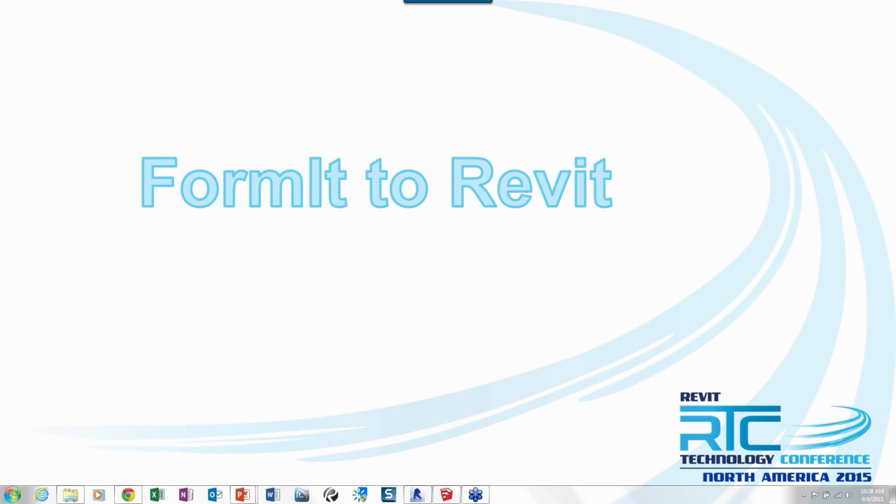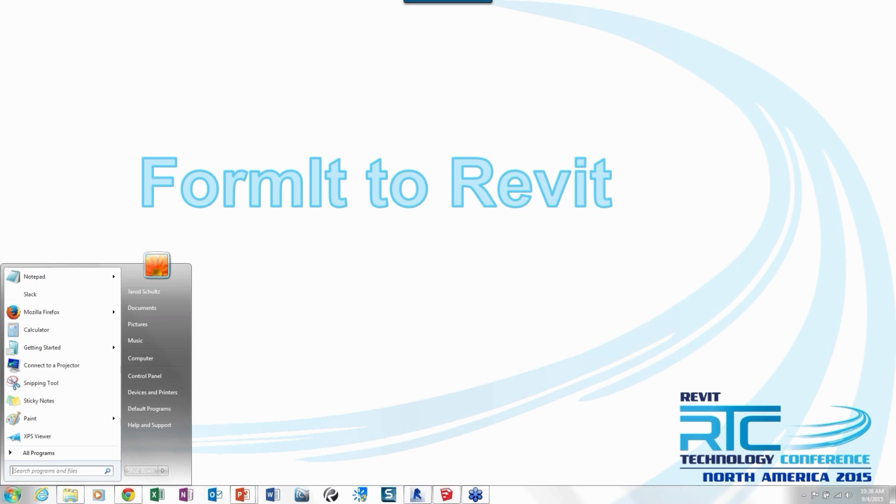The big thing too, when you're working with SketchUp, is that it's got to be watertight, and there is a nice little tool built into FormIt to show you that. So this is great not only for SketchUp but your own models, because early on when I started working with FormIt and working with Tobias, I was definitely breaking a few things, to say the least. It was just because of how I was deleting things and how I was putting certain edges onto the surfaces. So it's kind of cool where you can turn that on and check yourself, and especially the display backface. So you turn these on, and it'll help you.